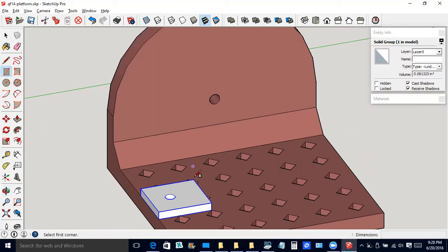And we want to make this vertical part of the bracket 1/8 inch thick. So I'm going to start with the corner over here, then go down to this corner here. Now we want from the edge of that rectangular solid to this black line to be 1/8 of an inch. And we could, but we also need to know what the other dimension is.